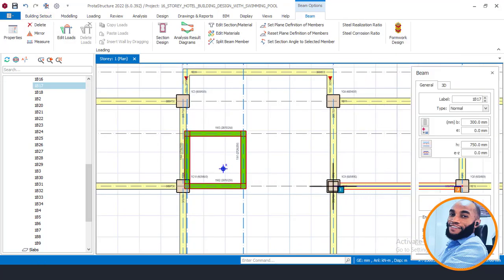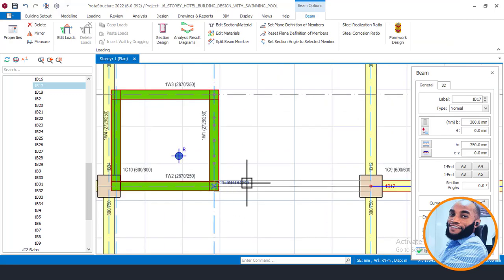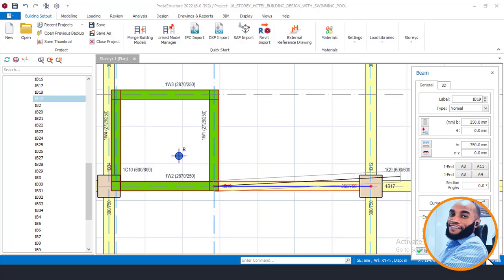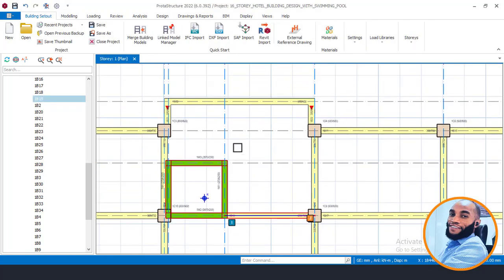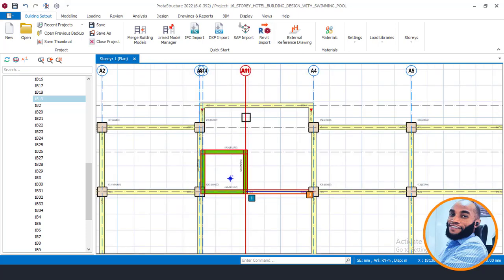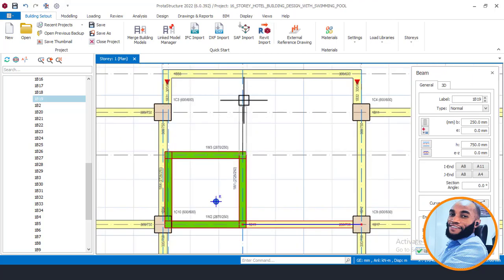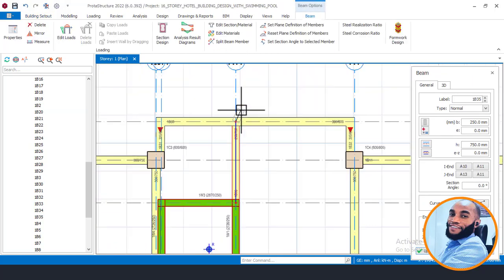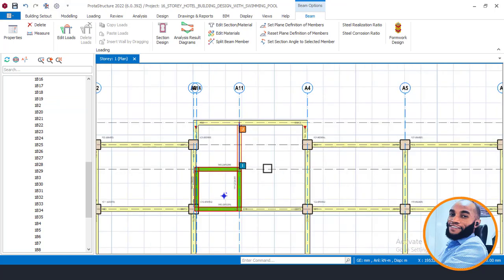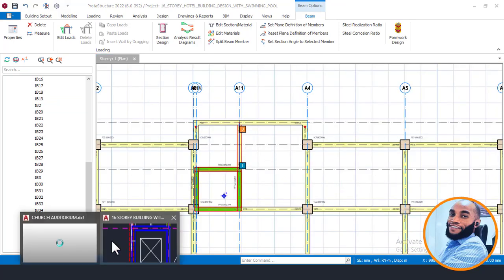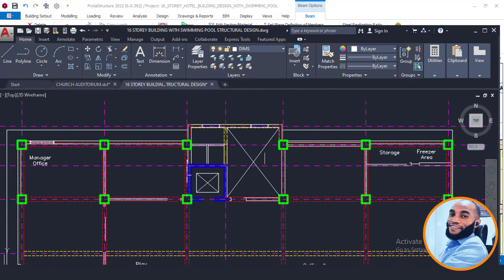So I'll come here right now and place a beam around this place and keep this here. Okay, that's fine. And I made this beam 250, so I'll say 250 for this beam, 250 to flush with the wall. Okay, that's fine. And there's also a beam running along this place here, so I'll take this property right now and place a beam here also and keep this here. That's fine. Because here now becomes our staircase void, as you can see directly on our plan view here.